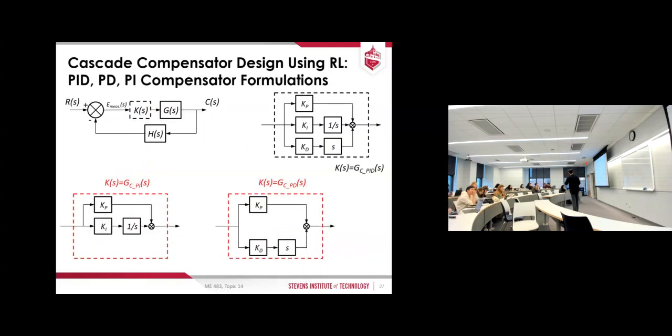And then in the project, one problem asks that, okay, remove Ki or Kd. So in this case, you remove, Kd is 0. What happens? This line is gone, cut, nothing. Then this is the PI controller design. Or you remove Ki is 0, then you remove this part, that becomes the PD controller. Okay? You did this PI in your project, and then you were asked to remove the Ki line. So you compared the P controller with the PI controller. Remember, right? You did that. Okay?